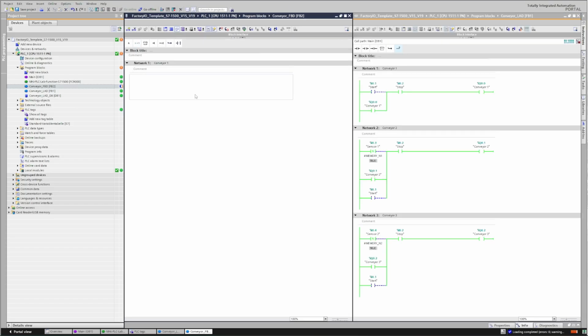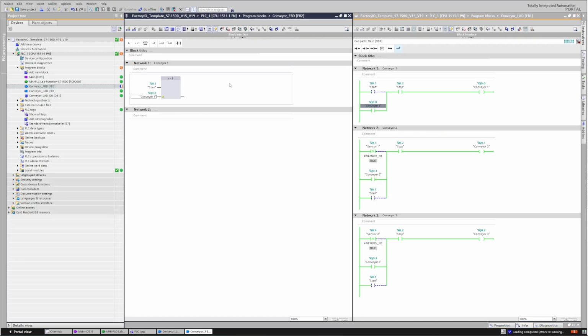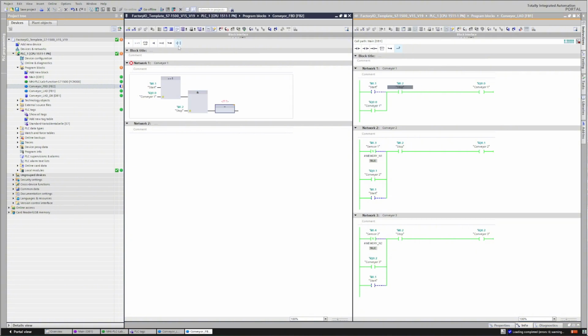And here actually we can check, like we can do exactly the same. Here, this one is an OR block, right? So we say OR, if it's start or Conveyor 1, and stop. And if it's stop, then we say the Conveyor 1 is on, right?